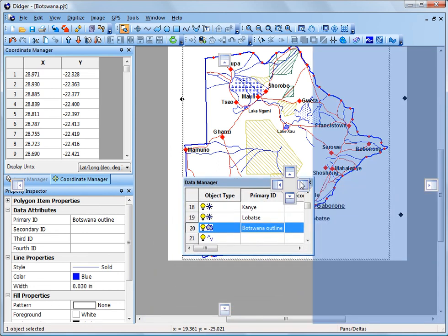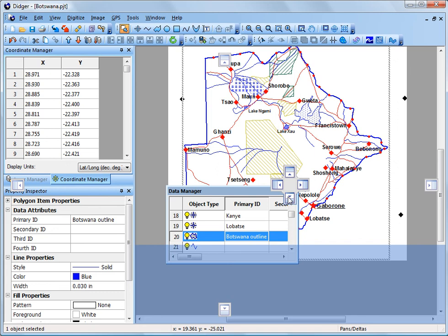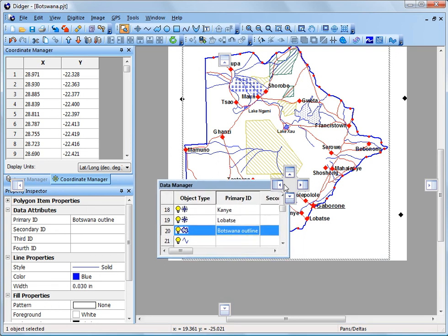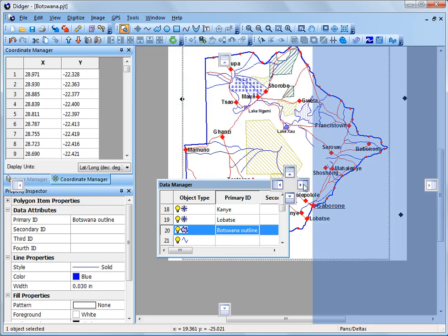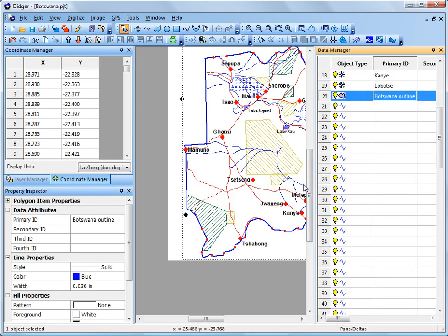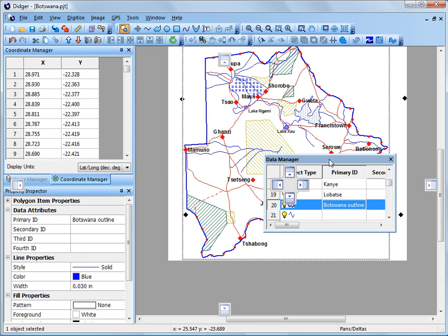When you're using the Office 2005 or 2003 or Native XP appearance options, the docking location options are shown by small buttons. Just move your cursor over one of the docking buttons and the new manager location will be shown by a blue shaded area. If that's where you want the manager to be placed, just release the mouse button. If not, move the cursor to a different location. Release the mouse button when the manager is in the location that you want.